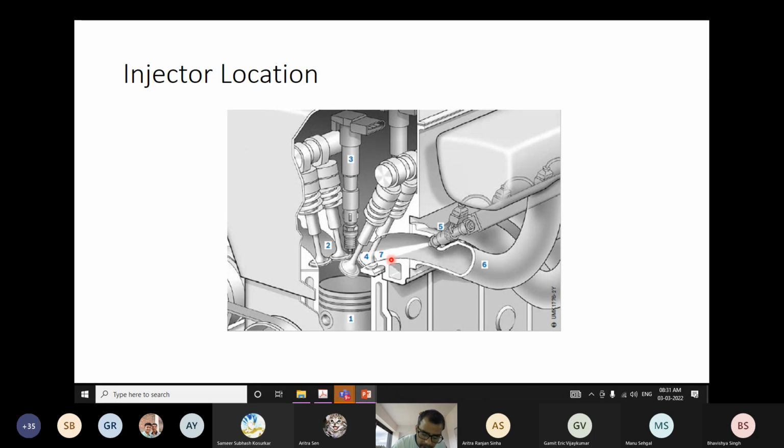When we are turning the key, the engine will take at least one rotation before it starts. It needs to take one rotation so that the engine will know where the piston position is. So one rotation is required to get the synchronization of all the signals. After that, there is a possibility that the engine can start in the second rotation of the crankshaft, if those are the best conditions.